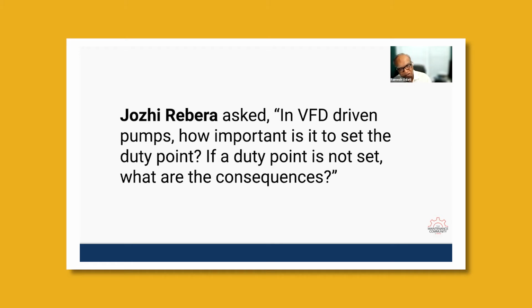Also, sometimes it's better to reduce the impeller size. That may be another way of doing things. So I would highly recommend talking to a pump expert or the VFD vendor, wherever they bought it, and asking why they are asking for that.